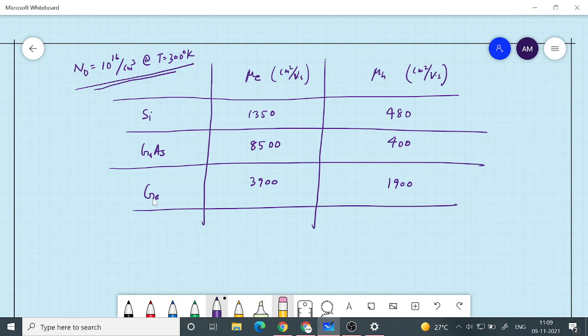That means in the design part, the sizing of the device, we need to make the PMOS devices 2.5 times larger in order to get the same performance. So those are some of the things which will come out of these differences in the mobility for electrons and the mobility for holes.